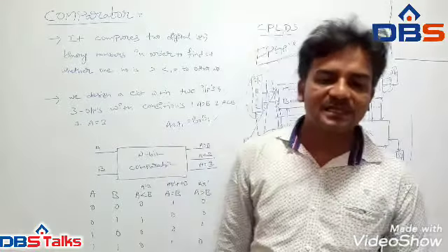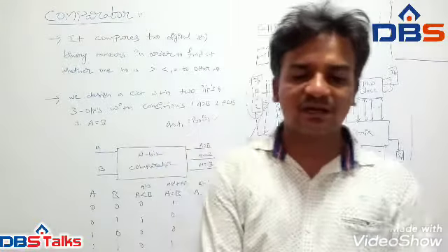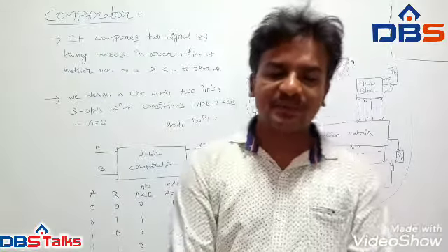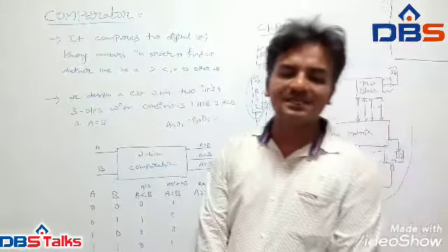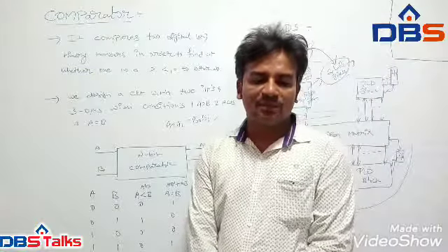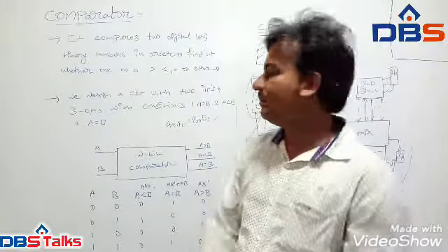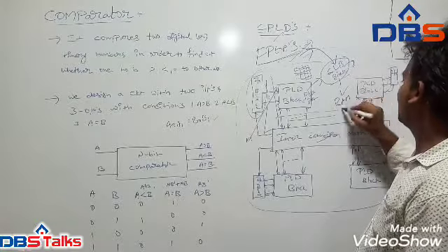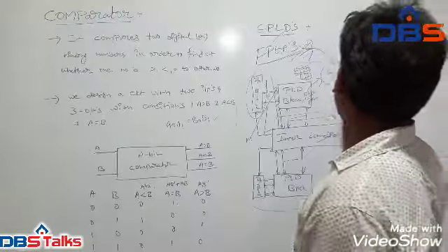FPGAs are better for more complex applications, while CPLDs are not better for complex ones and are better for simple devices. FPGAs are RAM-based digital logic chips, while a CPLD is EEPROM, that is, an electrically erasable programmable read-only memory based logic chip. The CLB supports RAM, read and write memory capability.